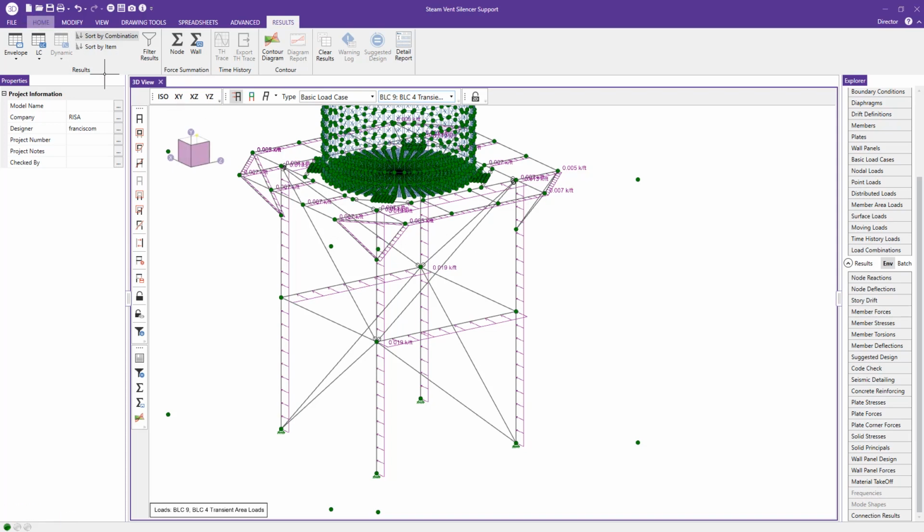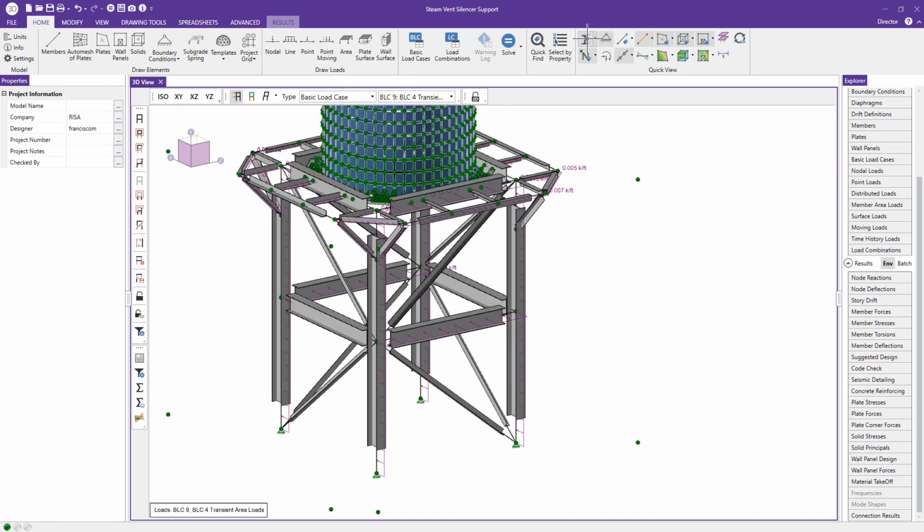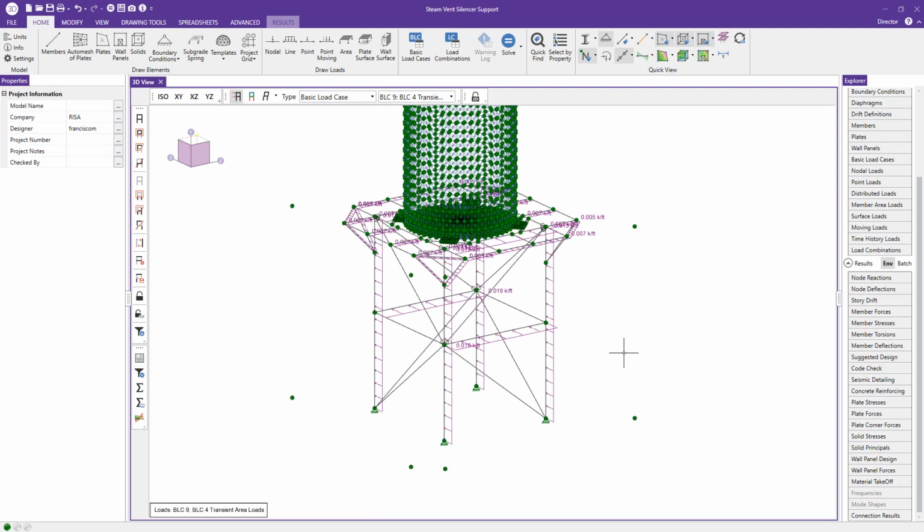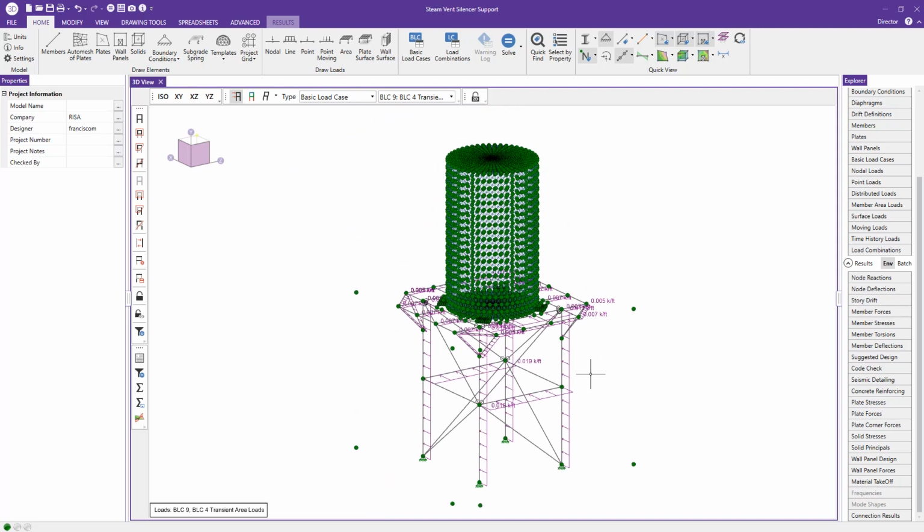So if I render this, you can get an idea to remind you of where we were. Obviously these wide flanges have a much larger surface area for the wind to contact, and then this angle is going to have a little bit smaller. If I unrender this, we can see that this line load is drawn proportionally. This is decently large, and you can see they get a little bit smaller as it goes to a smaller projected area for that wind. That's going to make your life really easy, so the program will calculate those loads for you.